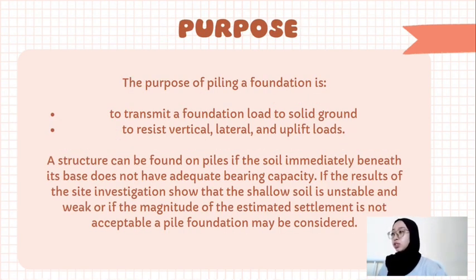Next, we move to the purpose of the piling. The purpose of the piling is to transmit a foundation load to the solid ground and to resist vertical, lateral, and uplift loads. A structure can be founded on piles if the soil immediately beneath its base does not have adequate bearing capacity. If the result of the site investigation shows that the shallow soil is unstable or weak, or if the magnitude of the estimated settlement is not acceptable, a pile foundation may be considered.